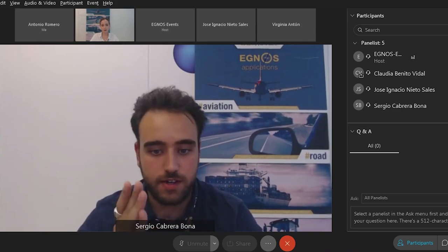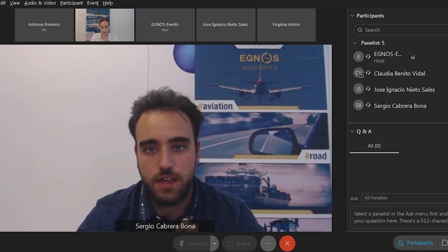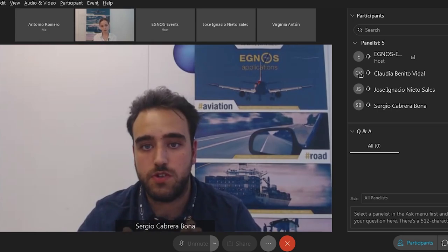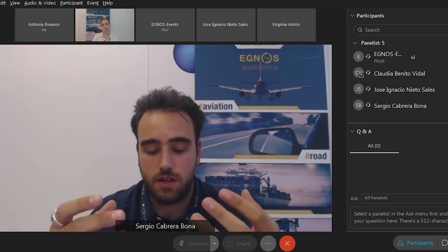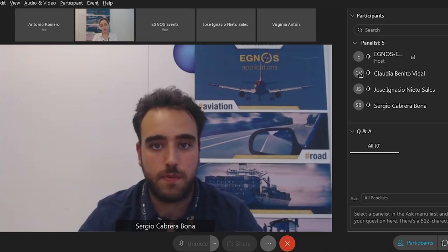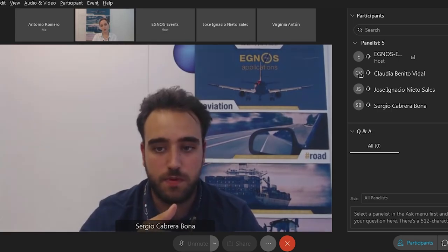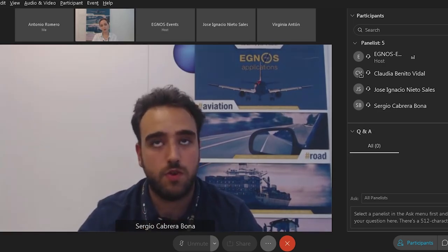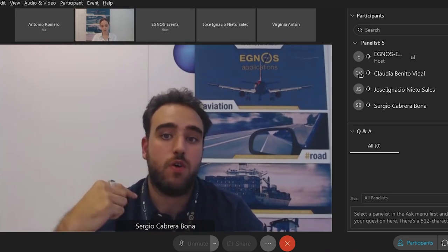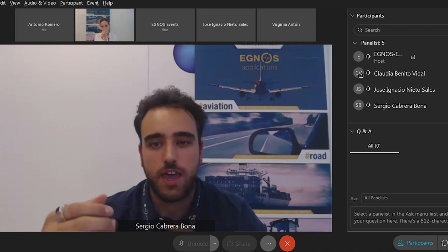So if the alternate airport that you define is farther away than another airport that has some kind of LPV procedure published, you will still be able to perform a precision approach procedure to an alternate airport that is closer than the previous alternate, and therefore you will have to load less fuel from the beginning of the flight, and that applies to the whole flight, so you will be reducing fuel, CO2 emissions, and also money.